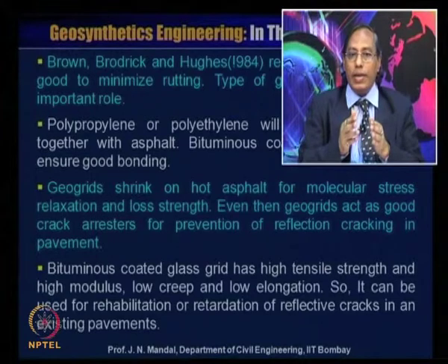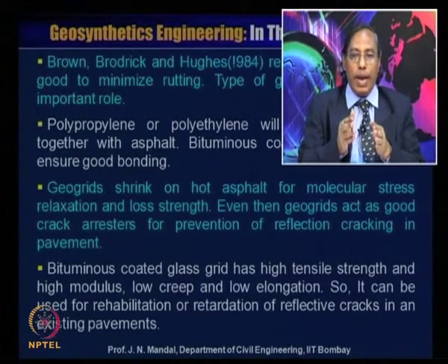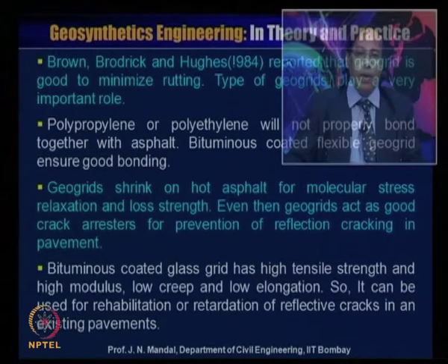Bituminous coated glass grid has high tensile strength and high modulus, low creep and low elongation. So, it can be used for rehabilitation or retardation of reflective cracks in an existing pavement.